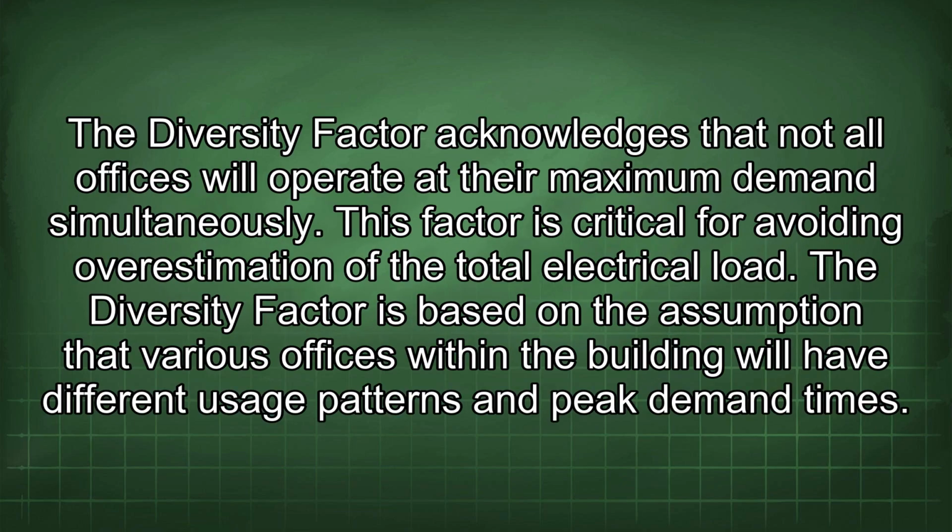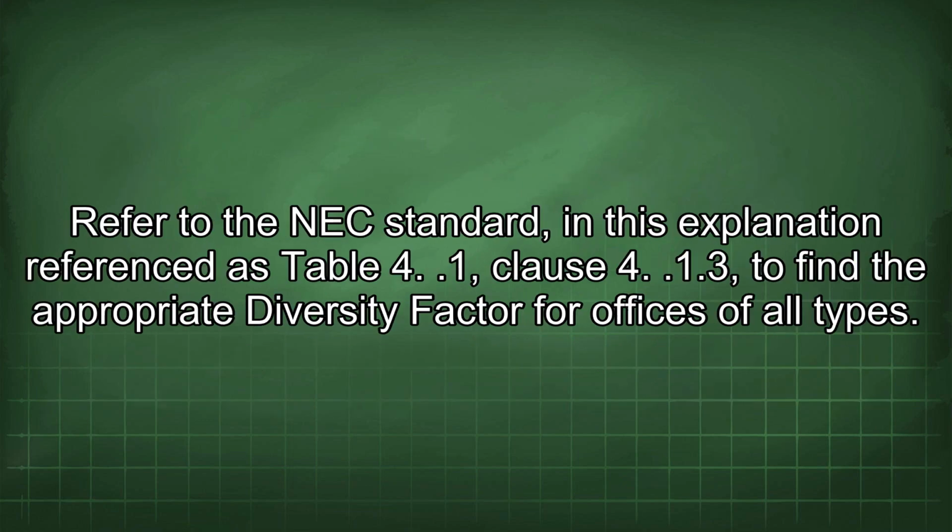The diversity factor acknowledges that not all offices will operate at their maximum demand simultaneously. This factor is critical for avoiding overestimation of the total electrical load. The diversity factor is based on the assumption that various offices within the building will have different usage patterns and peak demand times. Refer to the NEC standard, in this explanation referenced as Table 4.1, clause 4.1.3, to find the appropriate diversity factor for offices of all types.